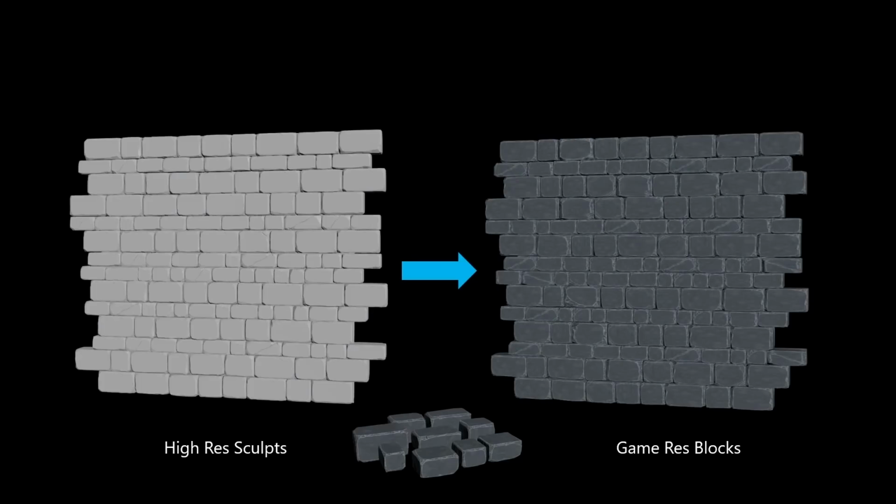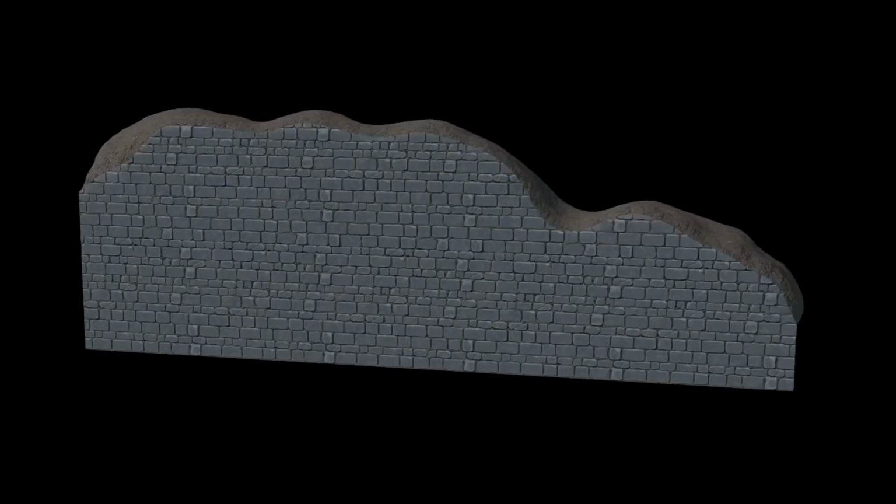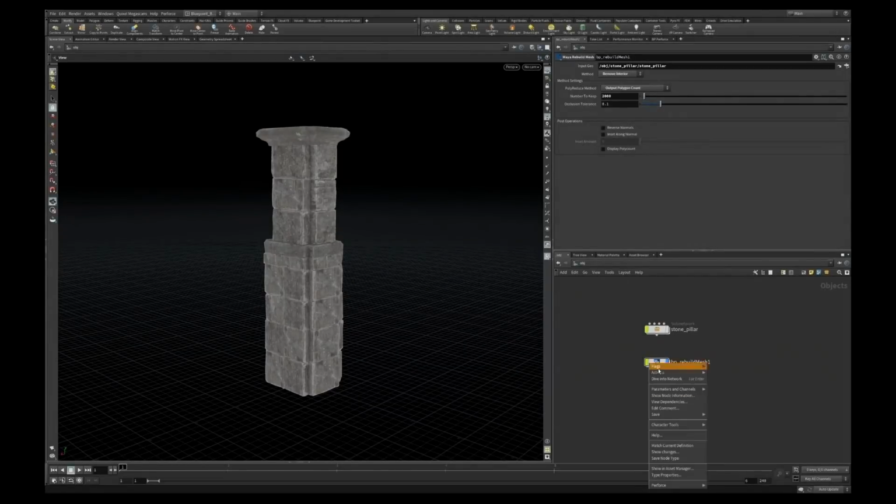Basically, I'm taking the exact brick pattern. Like, this is a tileable brick sculpt. Brick pattern. Yeah, so if I get the brick pattern, or I make it for them to match it, then that brick pattern I just copy across in the same location as where the UVs are laid out in the 0 to 1 space. And then because I have the brick pattern and the bricks are already in place, it's a no-brainer. It's a really simple solution, and it just looks a lot more challenging than it actually is. Yeah, that makes a lot of sense. Good. That's clever. Nice.